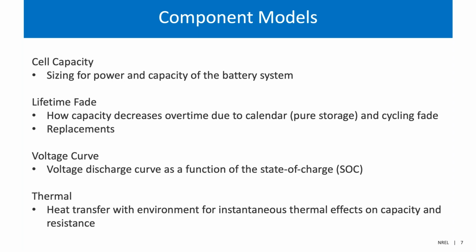The voltage curve is a function of the battery state of charge, operating current, resistance, and capacity. As batteries age, the resistance increases and the usable voltage range decreases. With higher currents, especially for lead-acid batteries, the voltage drops quicker, reducing the usable capacity. Temperature also plays an important role in the recoverable capacity loss.